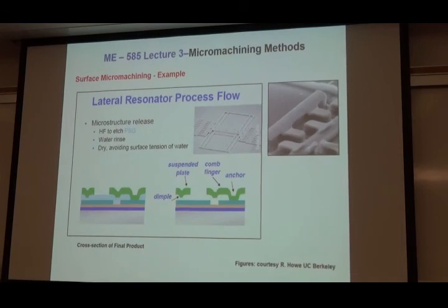So I had my PSG, I did a lithography on the PSG, I made openings over there, went in and then etched away the poly 0. Still I had the PSG left. Then once that was completed, I go and remove the PSG. Then you have this beautiful structure at this point. Does that make sense? Okay, it will make sense slowly, okay?